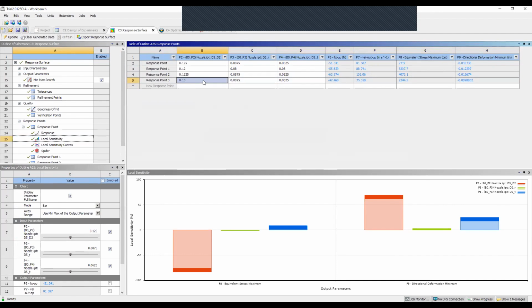Yes, I think this is probably one of the most useful, this table here that I'm playing with, because it's already giving me information rapidly. I can start just typing stuff in. You see over here, I changed the diameter from 0.1125 and I have it versus 0.1375. And you can see that the small diameter is creating a larger force and has more velocity.